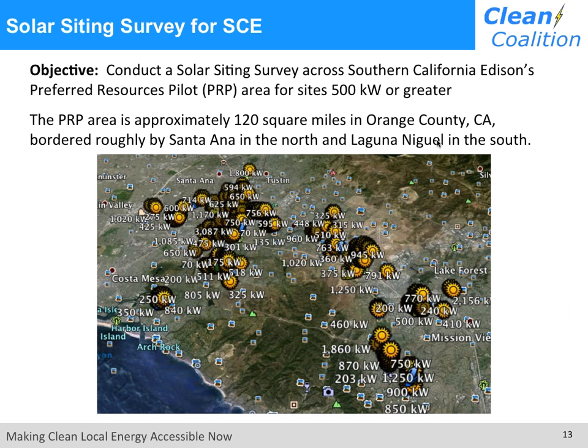So our methodology for doing the solar siting survey is really 5 things. We identify the appropriate sites in both size and position, including rooftops, parking lots and parking garages, as well as brownfield areas if they exist. We narrow down the candidate sites to the most feasible locations using estimates that exclude difficult or overly cluttered or overly shaded areas, so we're using the lowest hanging fruit, if you will, in terms of rooftops, parking lots, parking garages. We measure the most feasible rooftop square footage on a candidate site.